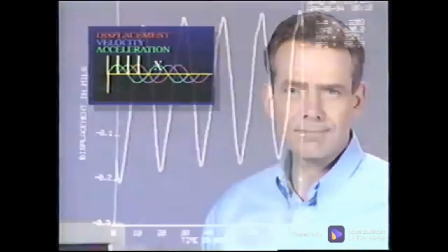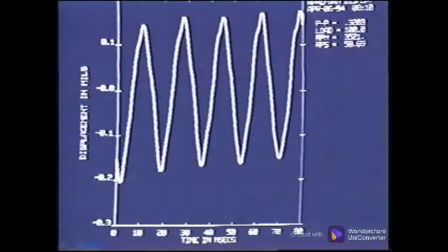The concept of the phase relationship among the 3 waveforms is an important one to know and can help you understand the necessity of using the same units throughout the procedure, such as a balance job. Let's compare the information the 3 waveforms tell us. This displacement waveform indicates an unbalanced condition in this machine. It is smooth and very sinusoidal, with no other energy apparent.